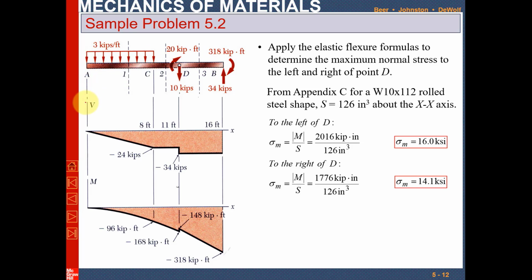So you have to draw a vertical line from the ends, and then you draw the horizontal line in order to show that the length of the beam varies along this axis x. Now let me write again. So we have V equal to minus 3 kips, M equal to minus 1.5 x squared. This is when x is greater than or equal to 0 and less than or equal to 8 feet. This was the first one.